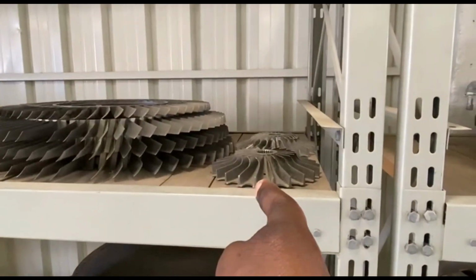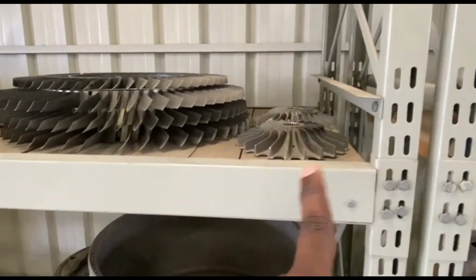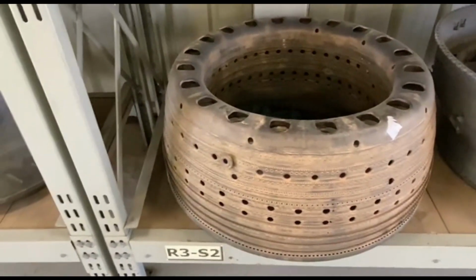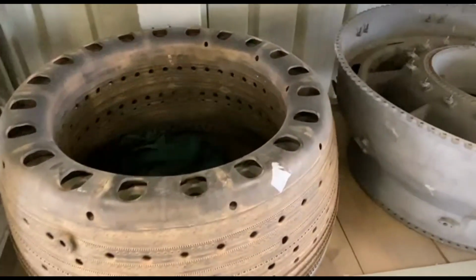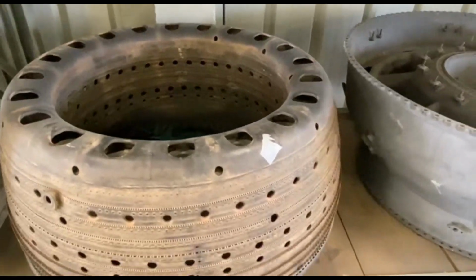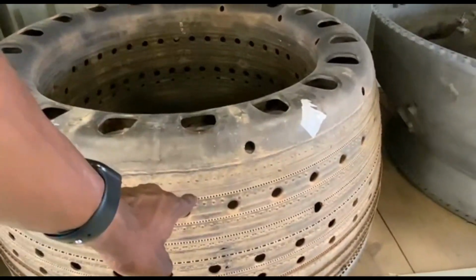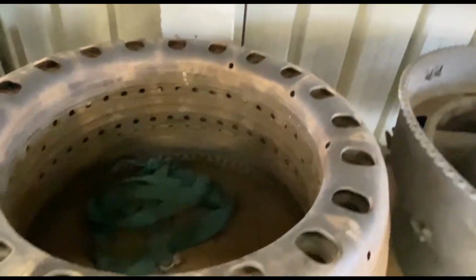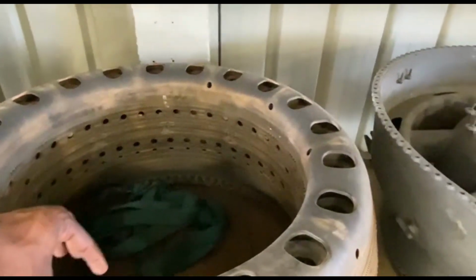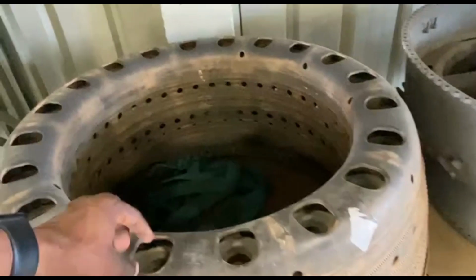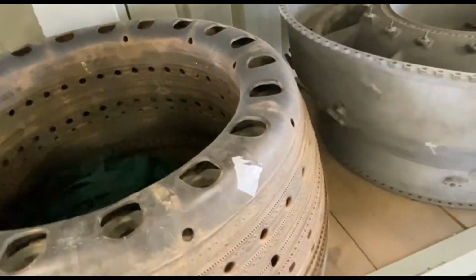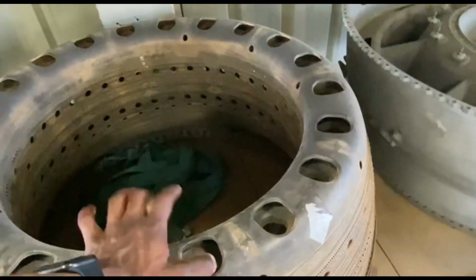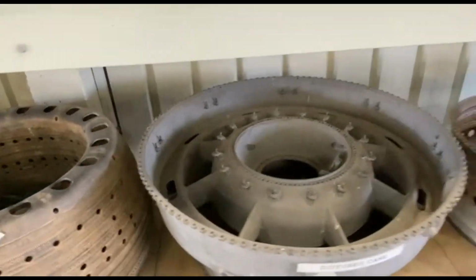I think it's an impeller type, if I'm not mistaken. And here we have the combustion chamber. You see, we have the combustion chamber, and it's very huge. These small holes are there for cooling, but the main ones are there to send the compressed air after the diffuser. It will come here, and you're supposed to burn it inside. And this one is normally an annular type of combustion chamber, if I'm not mistaken.